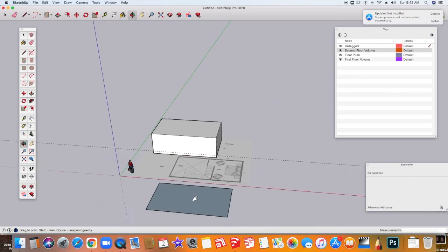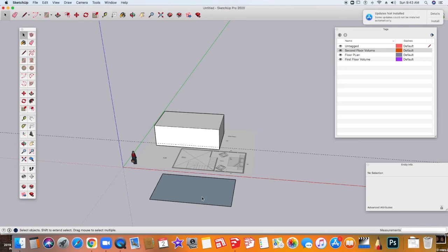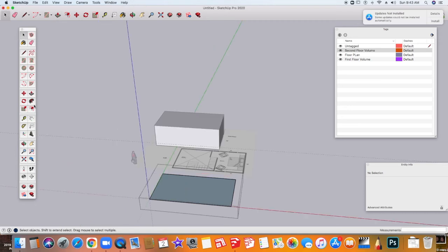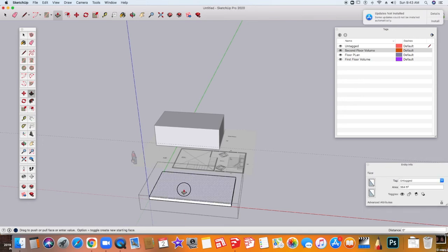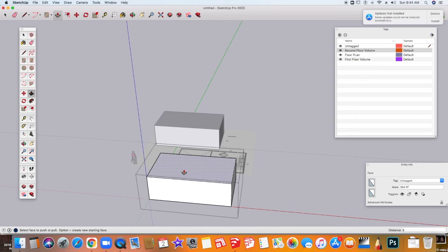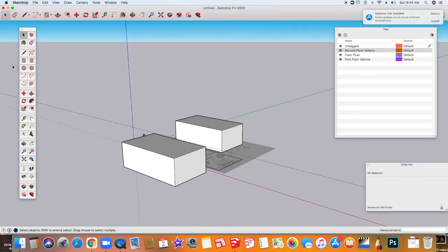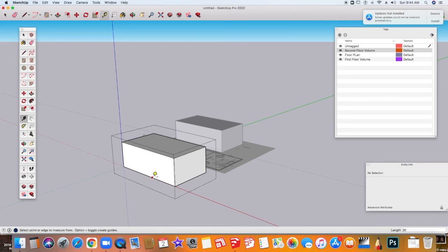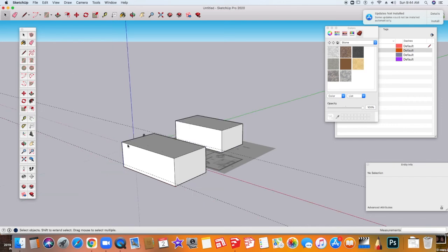If you have a second floor, there will also be a 1 foot space underneath, which will account for your floor joists. These are the joists that support the second floor. So we're going to do the same thing here. I'm going to go into edit mode. Remember, if you see that you can't do anything, it's because you're not in edit mode. I'm going to pull this up 1 foot, then pull this up another 8 feet because that would be the full height. So now I've got these two pieces. I'm also going to go into edit mode here and give myself a 1 foot high notation for where that floor joist would be. I did it in edit mode so that this guideline would actually be stuck with this group. So now I'm just going to put them on top of each other.